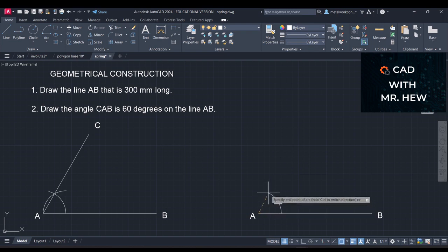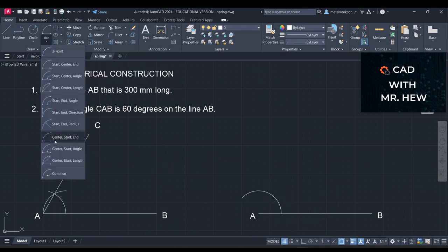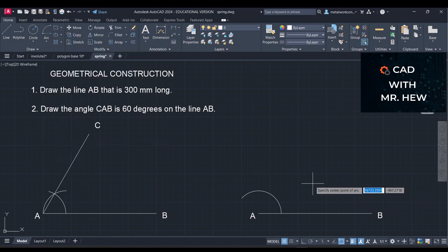So we're going to scribe our arc. So our pencil is going to make an arc. Now it doesn't have to go all the way up there because the 60 degree, as you can see, would be somewhere here. All right? So we're going to come again. The same radius that you put your compass to, you're going to put it at the intersection of this point. Right? I used 40, so you have to use about the same radius. Enter. All right, so watch now.